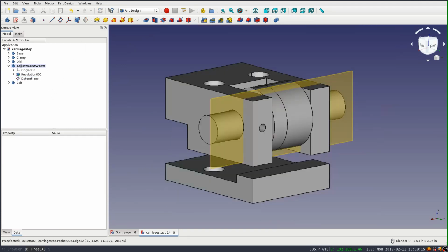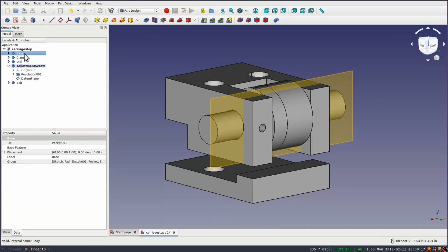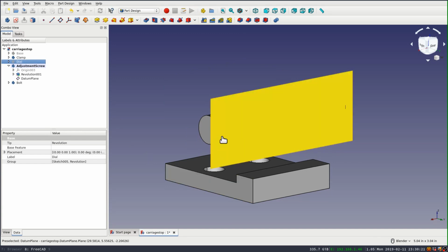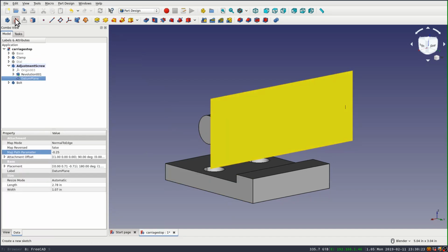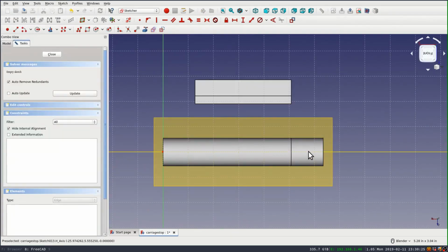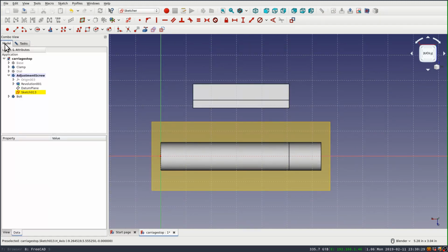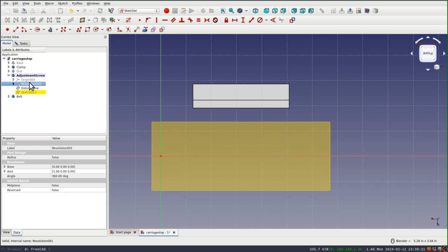So if I play with this and I set it to -25, that puts the datum plane on my front face, and then I can use that as the basis for a sketch to draw out the pocket that we'll cut in for the slot. So it kind of rotates around, and I got to play with this to get it in the right orientation, and it's easier for me to just turn off the tip of the body, so I'm working directly on the datum plane.